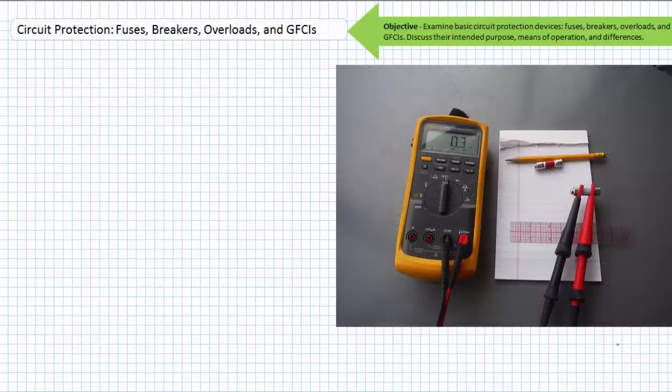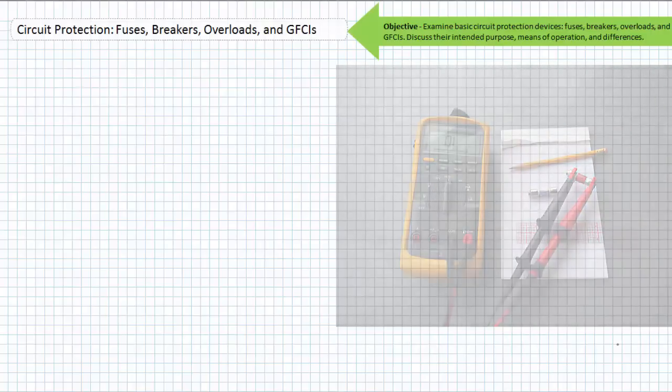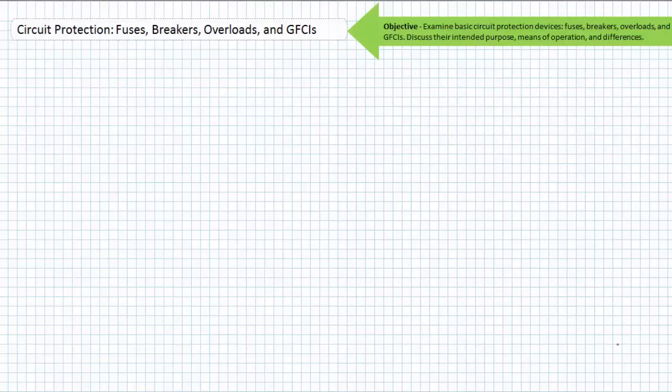The good one shows continuity between its 2 ends. This fuse is good. The blown fuse with the red band shows over limit or extremely high resistance between its 2 ends. This fuse is blown. If this is a troubleshooting scenario, the fuse is not at fault.